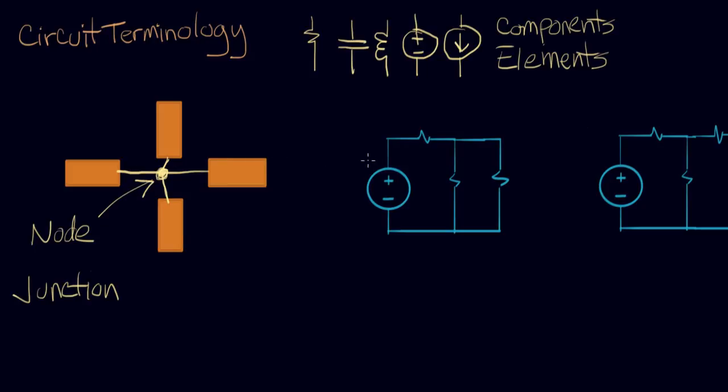We're going to go over to this circuit here and we'll identify the nodes. This is a little more normal looking, tidy circuit. Here's a junction right here between a resistor and this voltage source, so that's one node. If I move over here, I see resistors connected together by ideal wires, so that forms one single node, like that. So that's our second node. And down below, same sort of thing. I see an ideal wire connecting the resistors and the source, so I can color that in, and that's node number 3. So this circuit has 3 nodes.